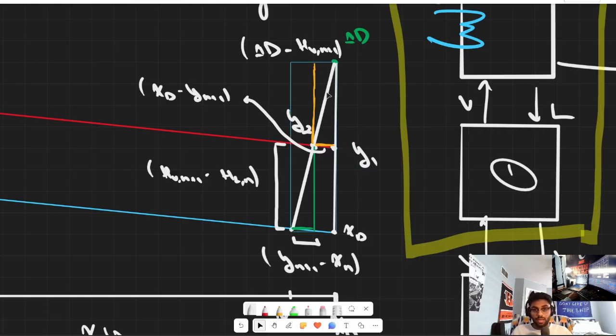So this straight line that intersects at this point is recognizing the fact that this is where our vapor composition for the stage below is going to lie. So this is for the rectifying portion of the Ponchon-Savarit diagram.